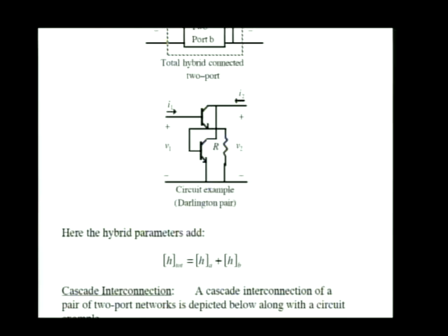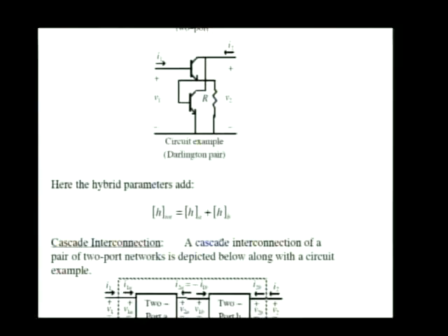three two-ports interconnected. Now let's say there's a fourth two-port connected in hybrid interconnection. Well, convert those y parameters I just found, now convert them to h parameters, and use the h parameters next to calculate the overall h parameters, including the fourth element that was hybrid interconnected, and so on and so forth, doing parameter conversions at each step.